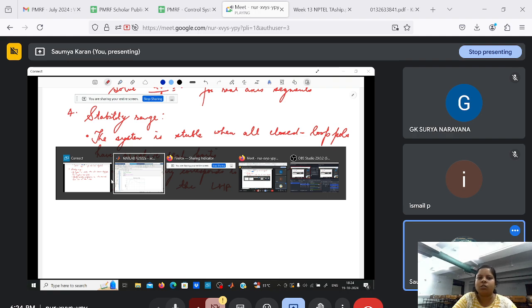So this is your root locus. Just this rlocus command was sufficient to give you the root locus. From here you can solve many questions and identify if things are correct or not. You see there is a pole at this point at 5. It goes to minus infinity. There are two poles here at 0 and what is the other value? Minus 2. 0 and minus 2, both of them come here. They break in. One branch goes here, one branch goes to this side.